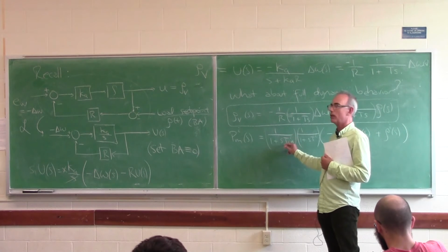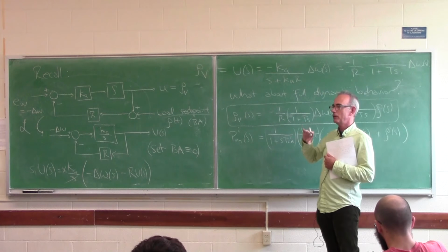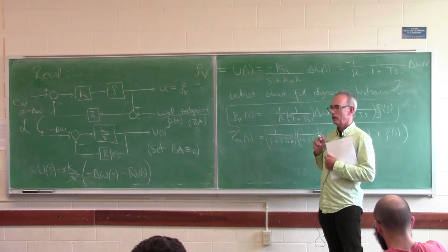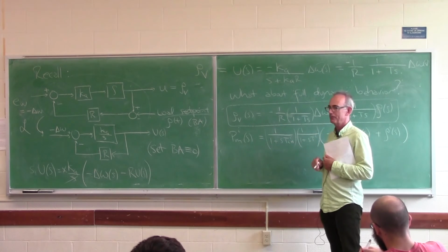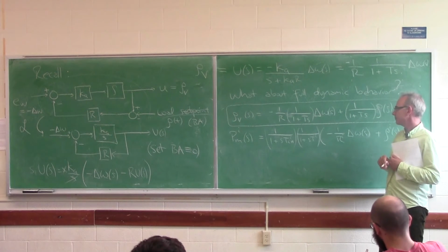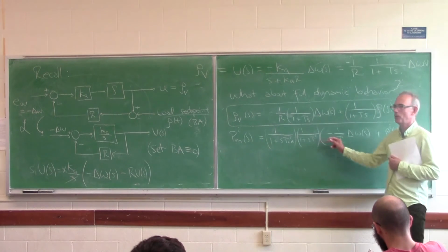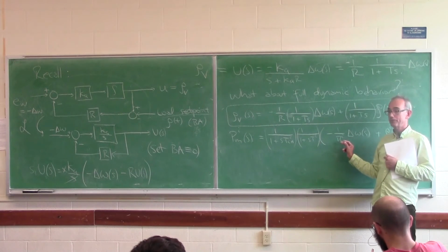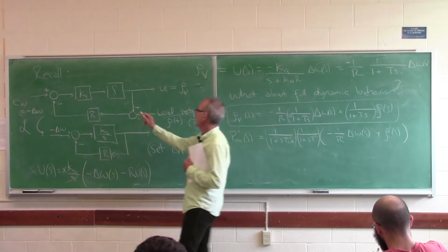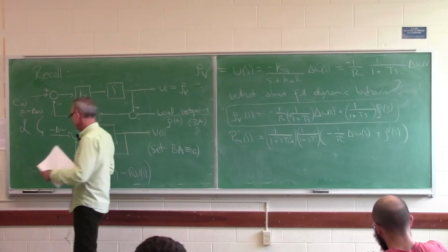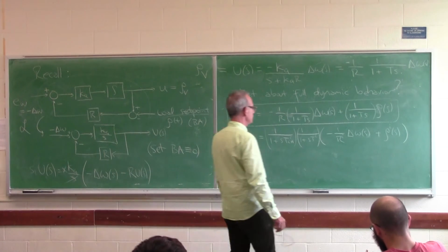TCH? Yeah, that's just a time constant for the dynamics of the transfer function from valve angle to power, mechanical power. And so this models the transient response, the steady state, everything. So that's the beautiful linear systems. You change a dynamical system to algebraic equations, but this represents a differential equation. All right. S is differentiation, 1 over S is integration. Just like I went from here to here. That's all I'm doing. All right. So it's a bit of a mess then, isn't it? So let's give it a name, I guess.